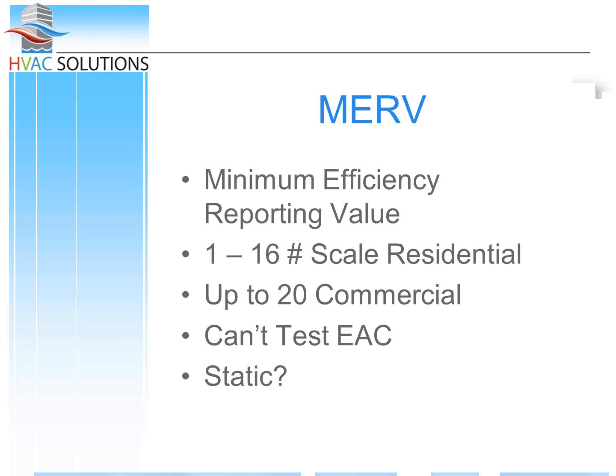And because there are so many issues with it, ASHRAE said, we're going to put everybody on the same playing field. Every filter takes the same test, and because of that, you get a number, and we get rid of that problem. So that is why the MERV rating was born. There are other tests out there. So we like MERV because ASHRAE does the testing, right? They set the standards. And if you're in the HVAC industry, you've probably heard of ASHRAE.